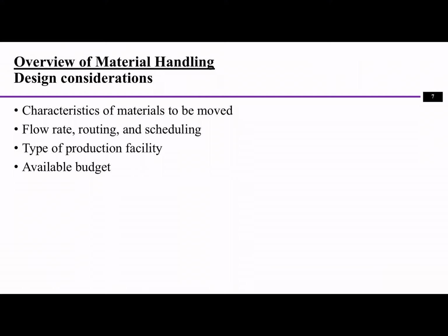if the material transportation is not very frequent, in this case you probably do not need a lot of automation in it. For example, you only need to transfer material from one station to another once a day, right? In this case, just use human labor, and they will be a lot cheaper than having an automated robot or AGV.